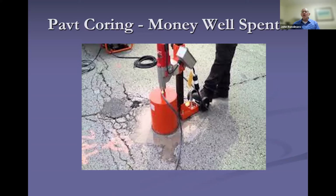And in the cold in place, you can go down probably as deep as, if you have a 6-inch asphalt section, you probably can get that deep. But typically you're looking at about a 4-inch recycling. But again, it's all asphalt.